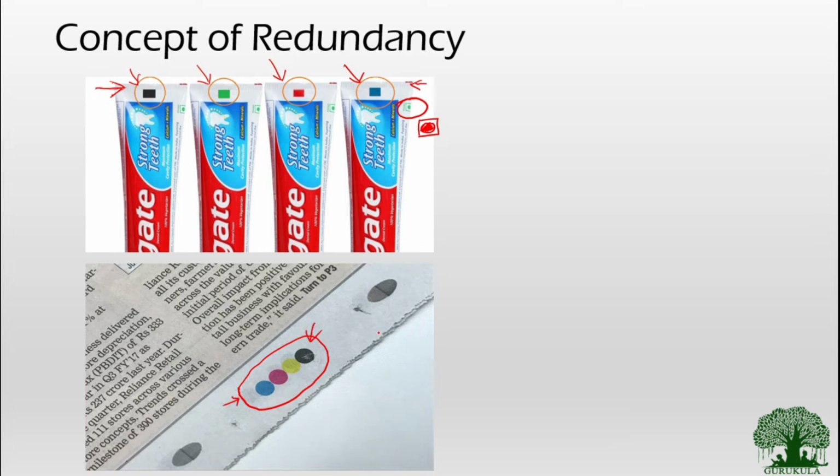Why is this printed on each and every single paper of the newspaper? These colorful dots represent all the various colors that have been used for printing that particular page. In case any toner is not properly functioning, if blue is not there, that represents the blue color is not being used in printing this particular paper, so that the color reproduction will not be that efficient.